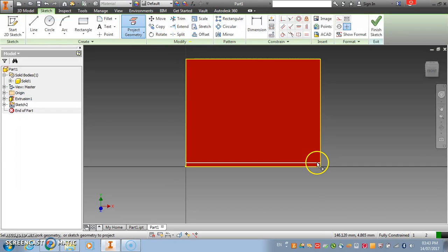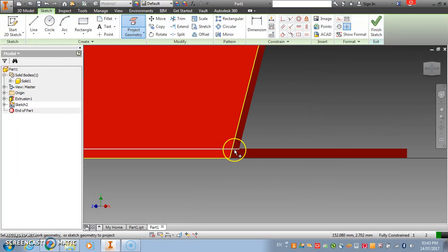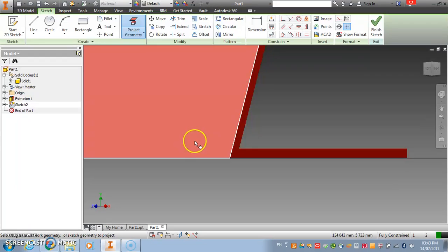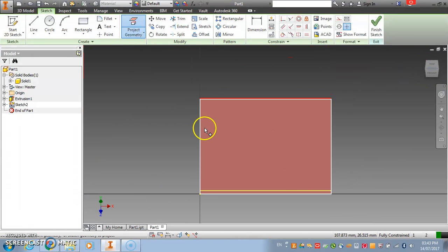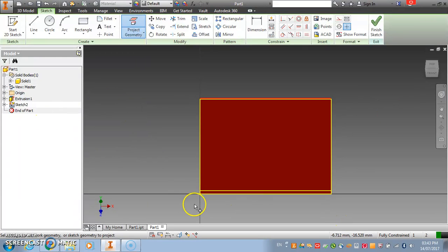And there's actually a little line here. This line is actually this line here, behind here. Okay, so I need to draw above this line so that when I do an extrusion cut, I will not cut this surface as well. So I have to click on this line so that when I'm drawing right now, I'll know where I should stop and where my limits are.